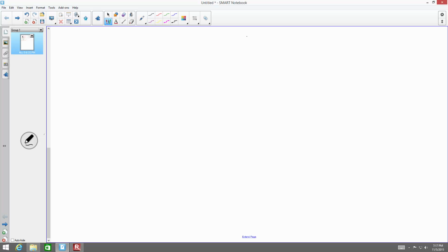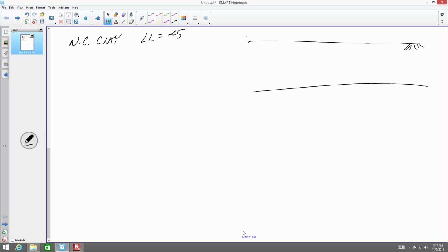Normally consolidated clay. A normally consolidated clay layer has a liquid limit of 45. The effective stress at the midpoint of the clay layer, so let's draw something up here. So here's our ground surface. At the midpoint of this layer, the effective stress is 2,000 pounds per square foot. NC, normally consolidated clay, N sub C. Estimate the compression index.